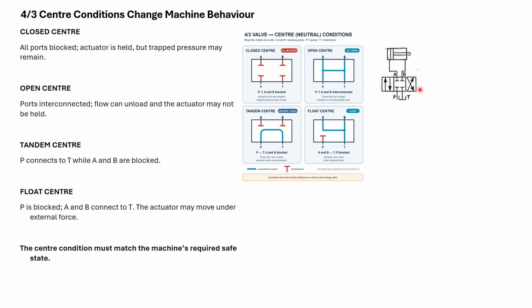For the third position, center conditions change the machine's behavior. Closed center: from here, this means closed. Closed center means the cylinder is held, but the trapped pressure may remain. Open center: ports are interconnected, flow can unload, and the actuator may not be held.